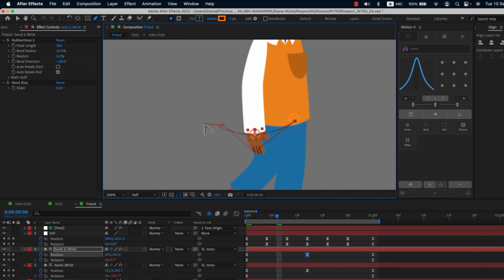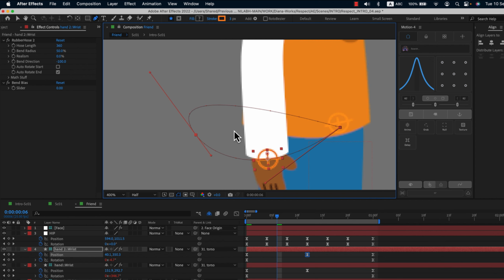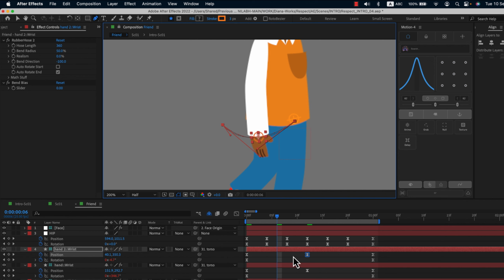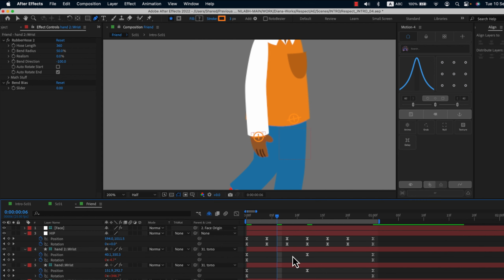You might notice that this is gone and pushed a little bit, so adjust it properly, both the curves. Now this is a good refinement. This is where you polish your animations. Okay, I don't want to add more keys in between and mess it up because it will not look smooth. So I'm doing it this way so that the path is very polished and smooth.